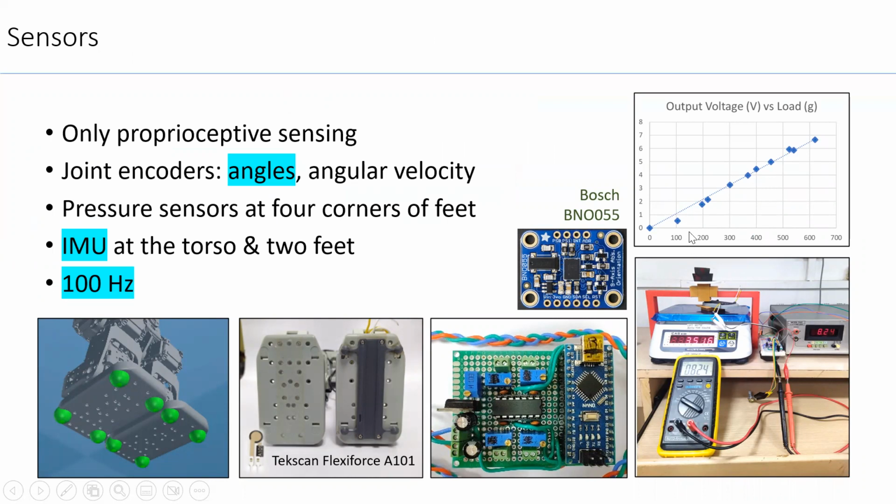We have some issues in calibration at the lower end because of the lightweight robot. So this robot weighs only about 1.5 kgs. So these sensors, when they are unloaded beyond the limit, do not perform well. So there are a few challenges here, but in the higher weight zone, they're working fine.